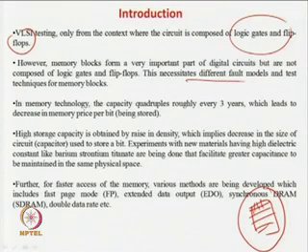In the case of a flip-flop, you can afford a somewhat larger area because it is non-symmetric and the purpose is a bit different. But in the case of memory, as it is only read and write operations, it is very symmetric in nature, and you have to compress as many bits as possible into a very small area. Philosophically they are different. That is why a different fault model and test techniques are necessary for the memory block, because of the very basic design philosophy and the memory block design.